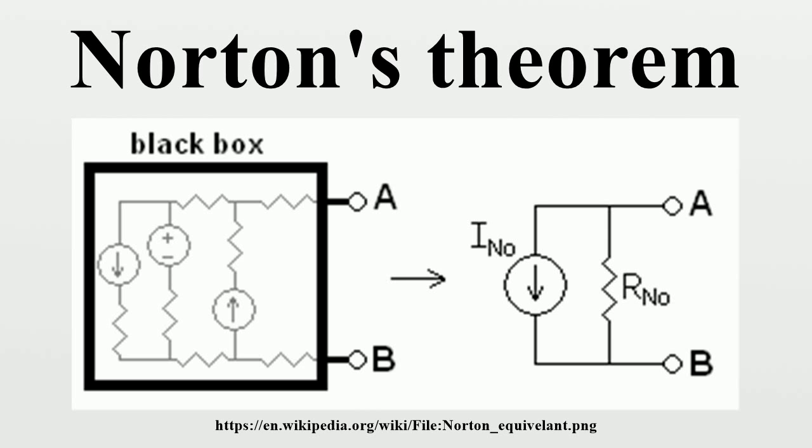For AC systems, the theorem can be applied to reactive impedances as well as resistances. The Norton equivalent circuit is used to represent any network of linear sources and impedances at a given frequency. Norton's theorem and its dual, Thevenin's theorem, are widely used for circuit analysis simplification and to study circuits' initial condition and steady-state response. Norton's theorem was independently derived in 1926 by Siemens and Halske researcher Hans Ferdinand Mayer and Bell Labs engineer Edward Laurie Norton.